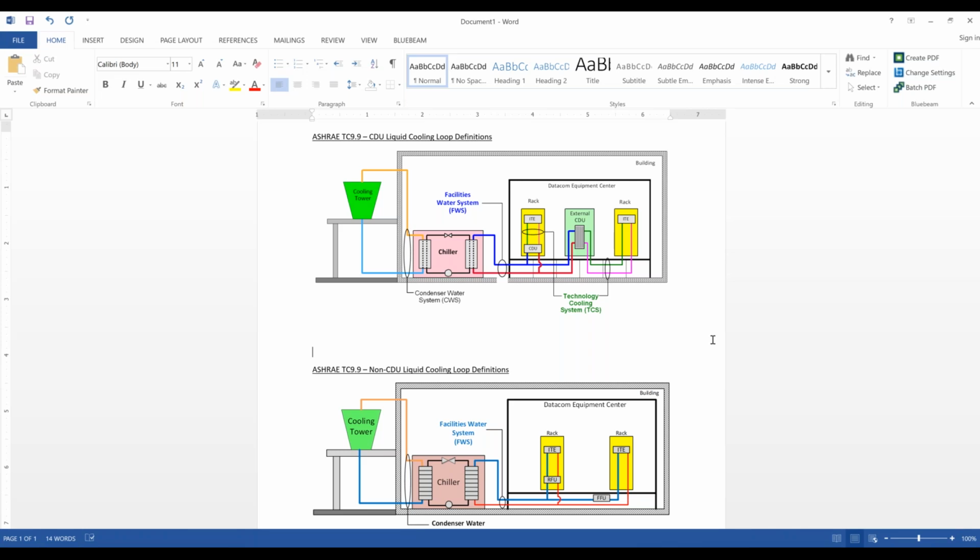So one thing that I want to talk about just very briefly, right, is obviously ASHRAE has done a lot of work on defining some of these liquid loops already. And I think that they've also done a pretty good job of creating guidelines on how those liquid loops should be administered. In particular, they have rules out there for wetted material, for flow rates, for water chemistry, et cetera. And all those things, I think, are also pretty relevant to the conversations that we're having here.